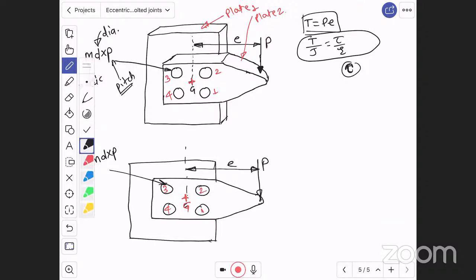And a very important note that you might have seen in engineering mechanics: any force can be transferred to any location, but along with the force we have to transfer the moment created by that force. If you want to understand this note in detail, that note you have seen many times in mechanics, let us understand it here. This force I can transfer to any location, and that location is the center of gravity. This force as it is I can put on the center of gravity G, but along with this force, whatever moment is created by this force about G, that also we have to put at G.